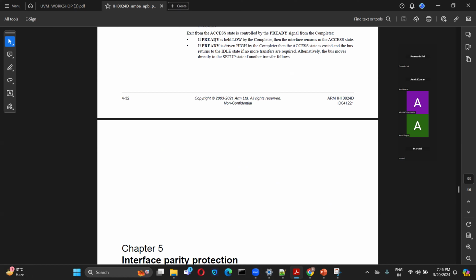I exactly didn't understand the skeletal part, what all the components. Skeletal part in the sense that we will create a test bench and code all the components, for example, the driver. We will not implement any functionality of the APB specific protocol, but we will just create the driver component, register everything in the factory, and try to print the topology and make sure that our test bench has no errors. So this way we need to code.